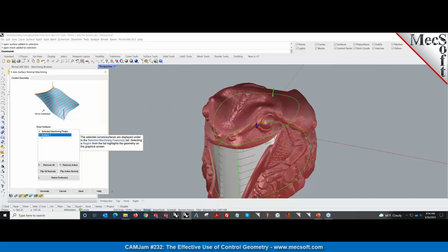So we need the surface to derive the surface normals on the cut pattern. So that gives us the cut pattern to position the cutter along. So that surface is used to define the surface normals as well as cut patterns.